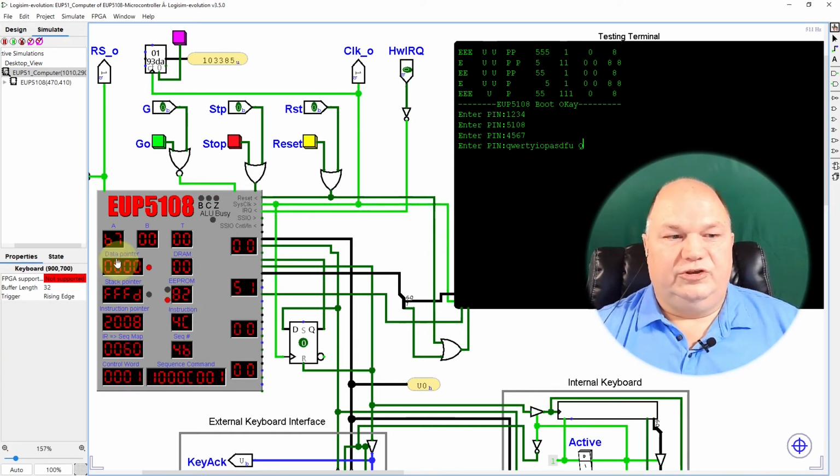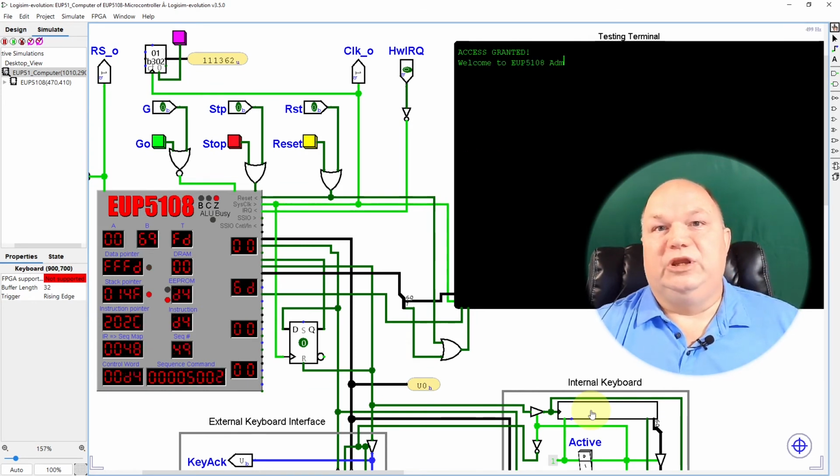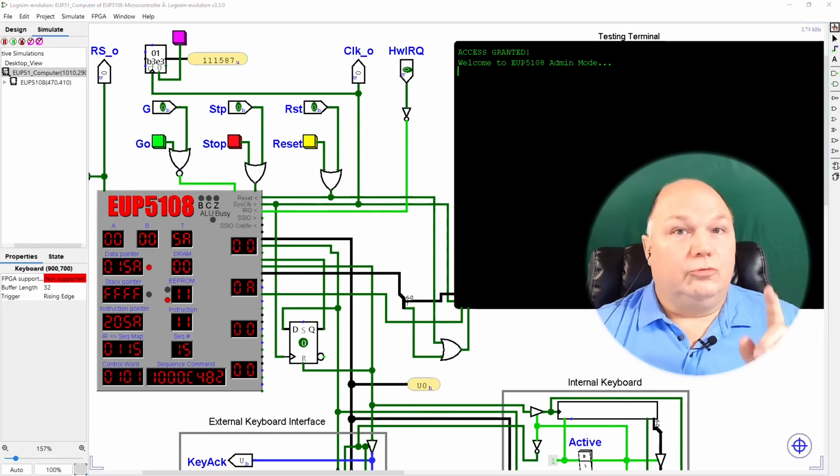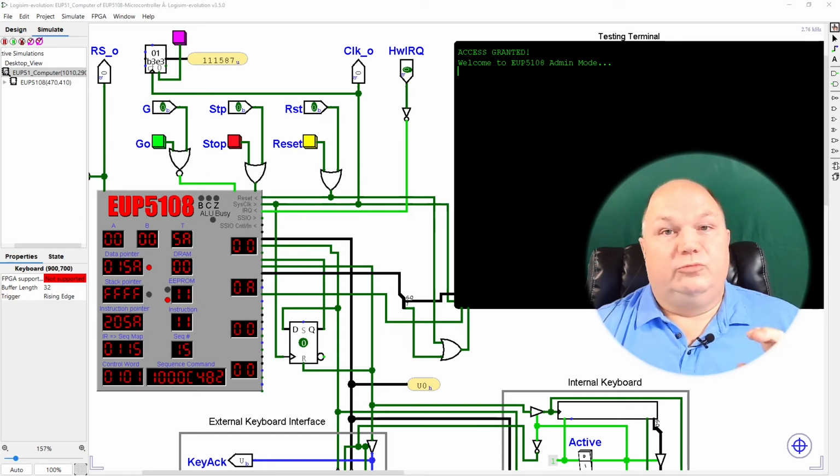So now, as you can see, our data pointer has gone all the way past memory and gone back around to 0. And when we hit enter to return from this function, we're going to return past the check on whether this is a valid pin and just get immediate access. So that's the basics of a stack overflow hack. So how did we know what address to put in? It came from our compiler's or assembler's map file, which is because we're effectively open source.